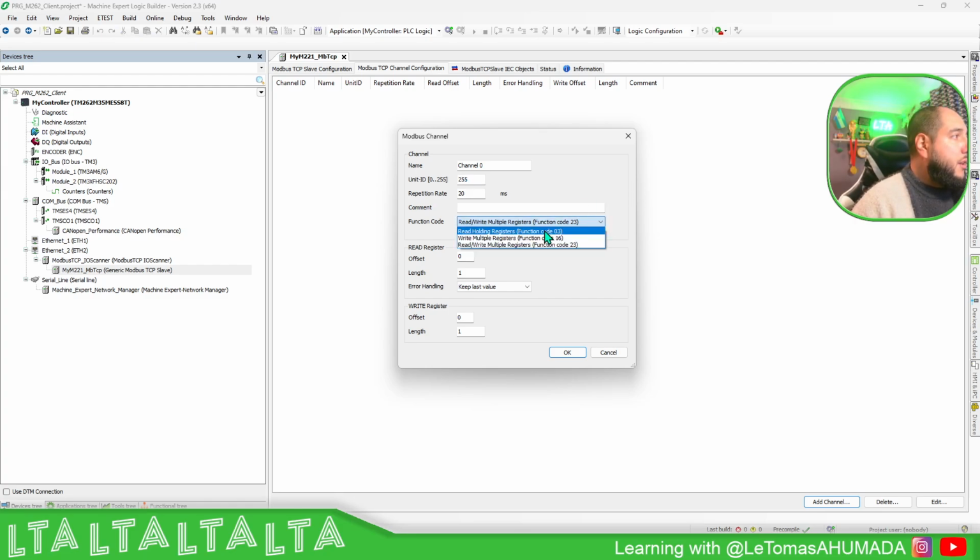Then I just need to define the read holding registers. Okay, read holding registers. In theory will be the one from 100. Okay, this is something that we need to check. So if this doesn't work the first time, you can probably read the information with an offset. So instead of having this, you're reading this. You just need to check if you are pointing to the right one. Here I'm going to read 5 registers. It's going to be channel read.